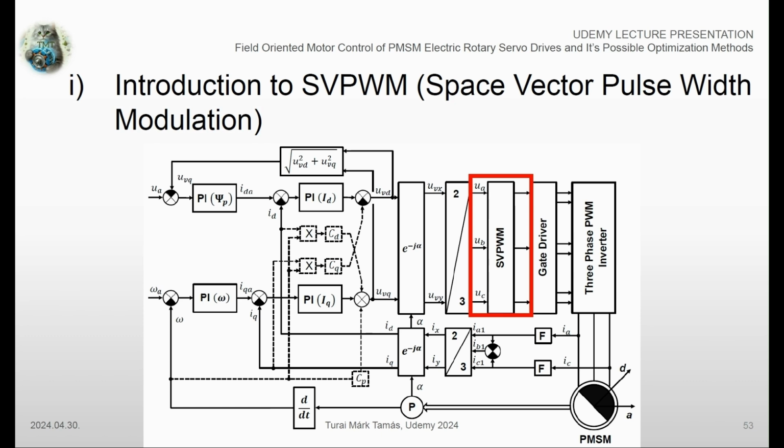This is the last part of the FOC algorithm, which means that the function software forwards these reference phase voltages calculated by the latter mentioned logic to the base software layer, which afterwards translates these demands to direct IGBT or MOSFET switching signals for the three-phase voltage inverter. In this video, we are going to cover the theoretical background on SVPWM with the help of the Park vector representations of the three-phase voltage inverters.